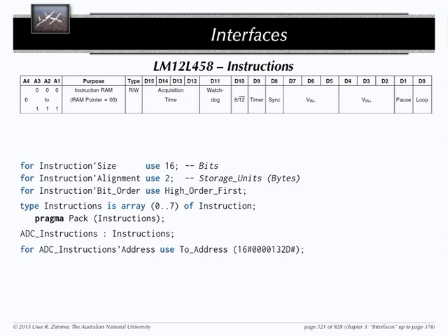Because you have to make sure by the whole design of your operating system, of your library, of your interfaces, that this cannot happen, and you are right, you cannot actually prevent that. If I would give this address to 5 tasks in my ADA programming environment, and all of these tasks are hammering my AO controllers unsynchronized, that's probably a really bad idea. And your device would probably go completely haywire from the non-atomic access to all the different registers which you have in there. So you have to make sure, usually, this is what is called then a device driver.